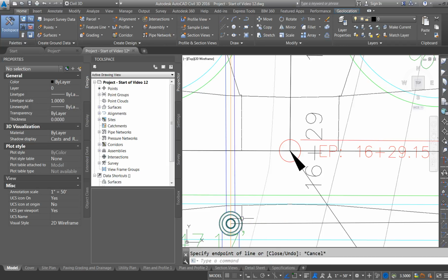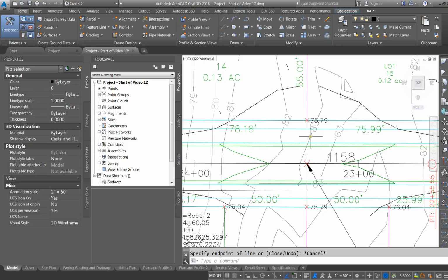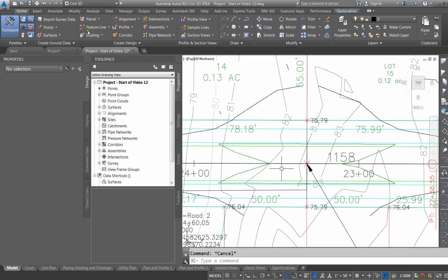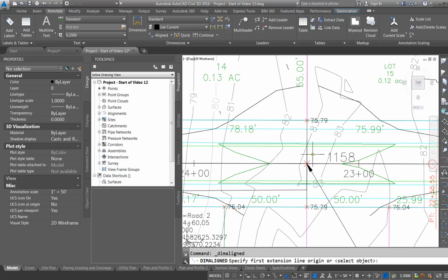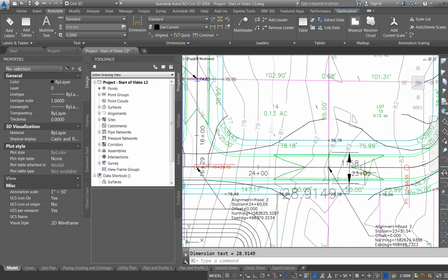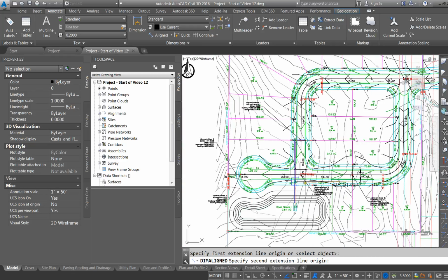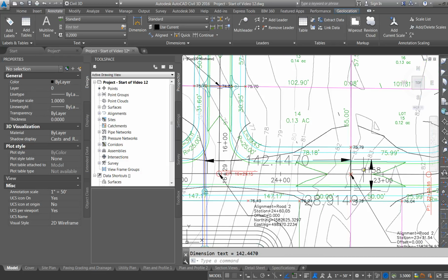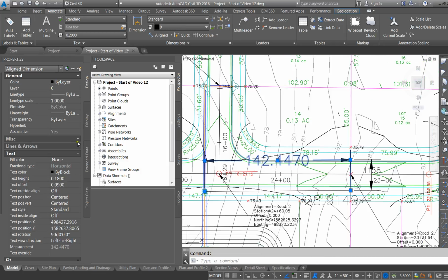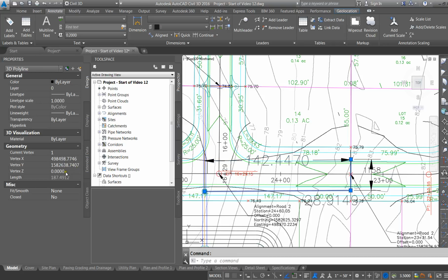So on this one, I take a look at what the spot grade is. So elevation again is at a 75. So on this one, what I would do is I would go annotate, and I would get the distance here, and I would get the distance here, and I would set the inverts. So my first invert is going to be a 70 because it's about 5 feet below. So I'll go ahead and use 70. My second invert is going to be the 69.93 because it's going to be the same distance for this one as it is over here.